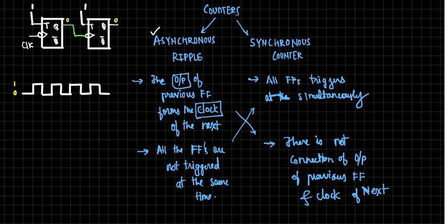Okay. Now let's take the flip-flops one by one. Where is the clock applied? First flip-flop. Okay. How is the clock changing? This is how the clock is changing. Now this is a T flip-flop and it will definitely toggle just because T is connected to 1. When will it toggle? When the negative edge of the clock appears, right? So negative edge, here. It toggles means if it is 0 it will become 1, if it is 1 it will become 0. What is the initial state?